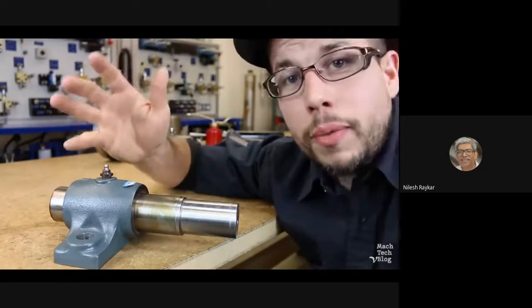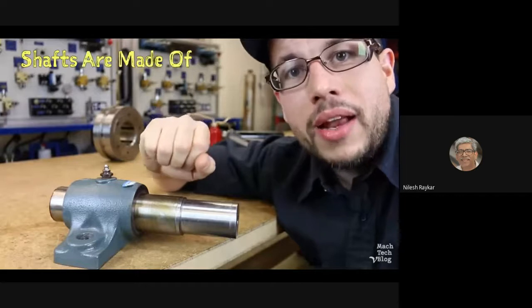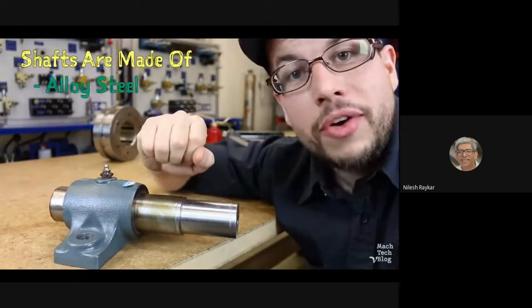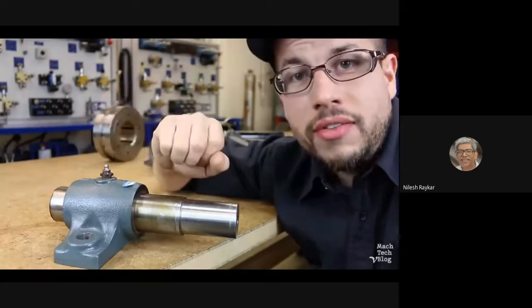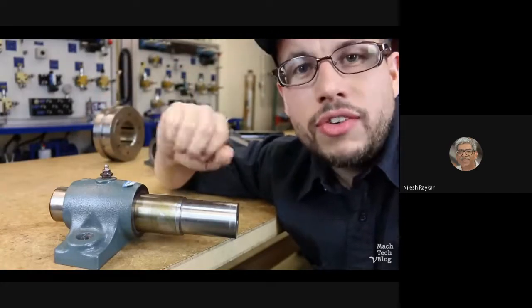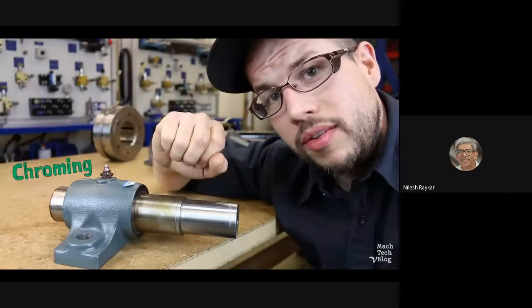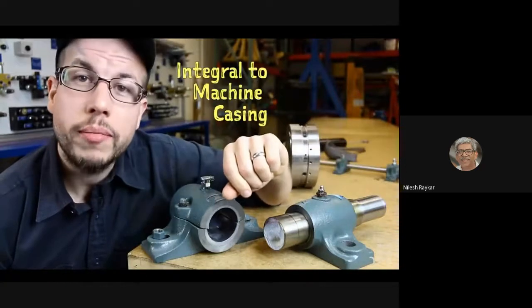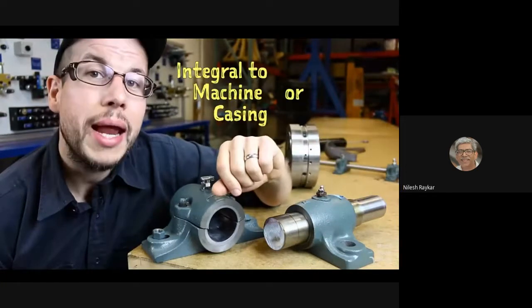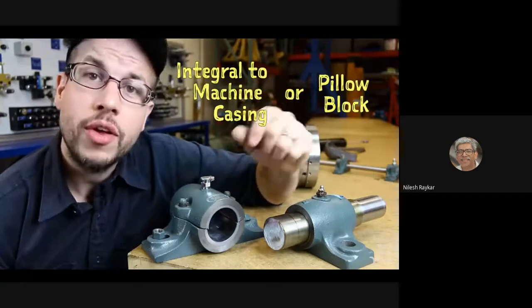Since the whole purpose of a shaft is to transmit power in a machine, it's always made out of a strong material like alloy steel or stainless steel. And sometimes the journal sections of the shaft get an additional extra treatment like chroming in order to improve hardness and wear resistance. The stationary component of the bearing can either be an integral part of the machine casing, or it can be a pillow block, which means that it comes as a separately mounted unit with its own base.